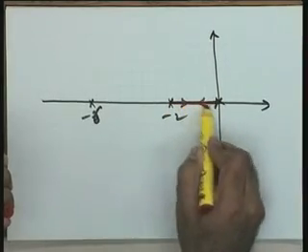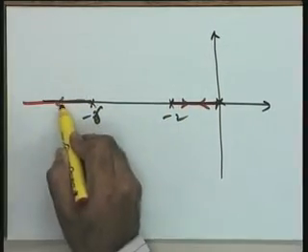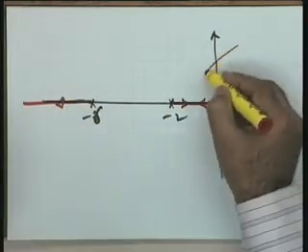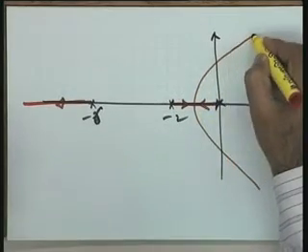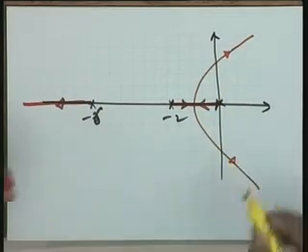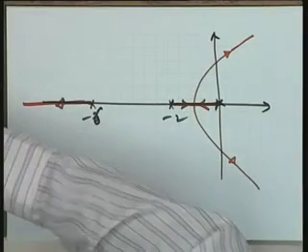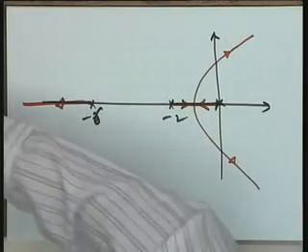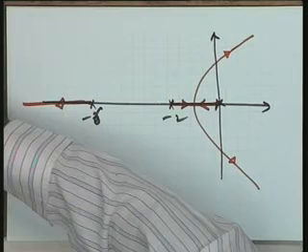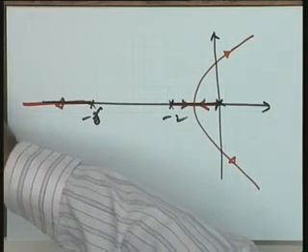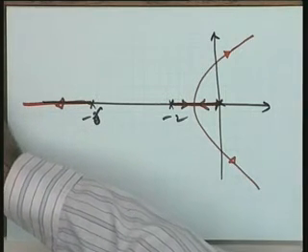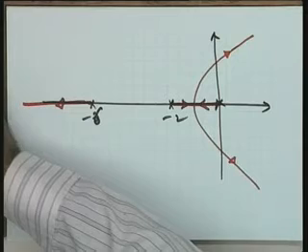You give me the answer to my question, please. If I place a pole at the origin, what will happen to both the steady state and the transient accuracy? First of all, comment on the steady state accuracy, please. If I place a pole at the origin, Kv is equal to infinity, meaning thereby that your steady state requirement has been drastically improved.